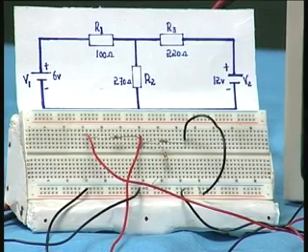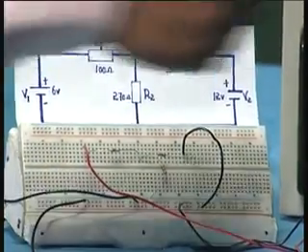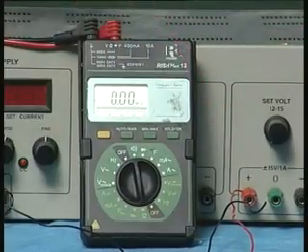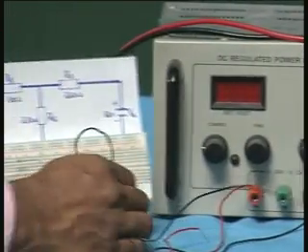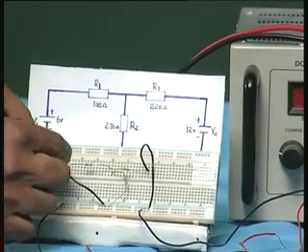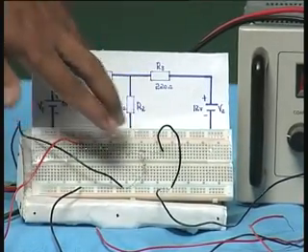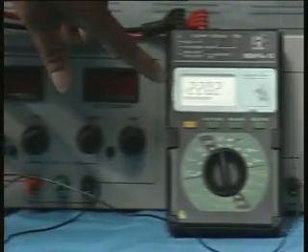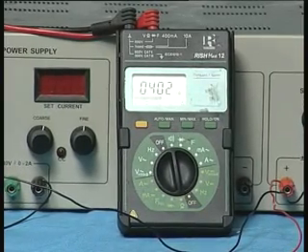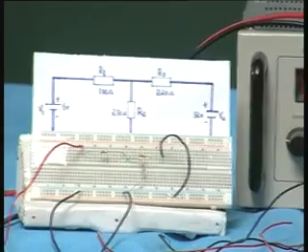You can actually also measure resistances if you want. For example, after connecting, you remember the total resistance, I can now put it in resistance mode and measure the resistance. I will switch off the power supply. Now I want to measure the resistance after shorting on this side. I want to measure the resistance across this point, total resistance. This is nothing but 100 ohms plus the parallel value of 220 and 270. I have a short here. Yeah, this 100 ohm plus 220 and 270 gives me around 219 or 220 ohms, that is a parallel.